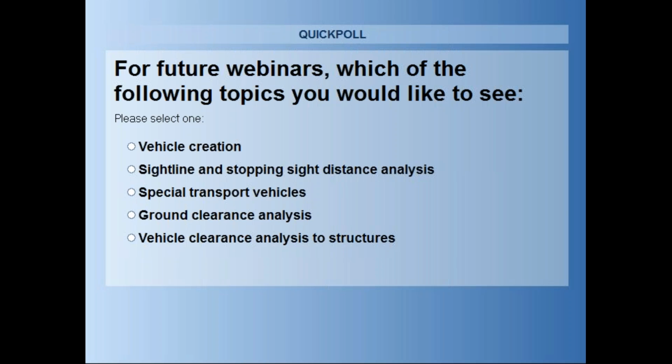Yes, it's only in a different way than AutoTURN. In AutoTURN, you control where the oversteer is triggered. In IntelliPath, what it'll do is IntelliPath uses the steering rate of the vehicle. So if it needs to oversteer to generate the movement, it'll oversteer.